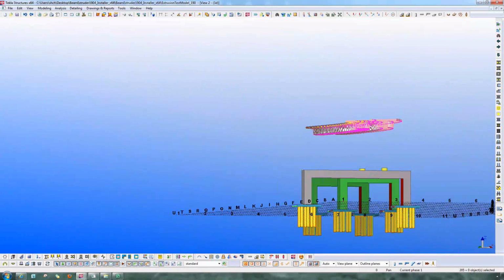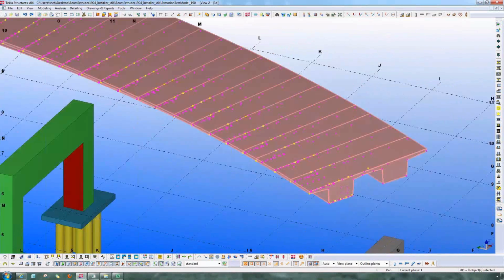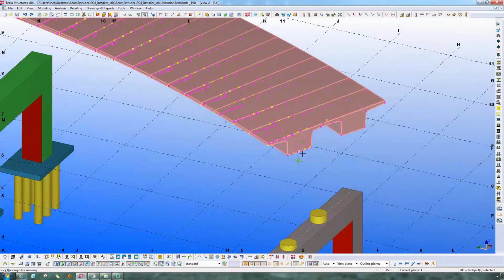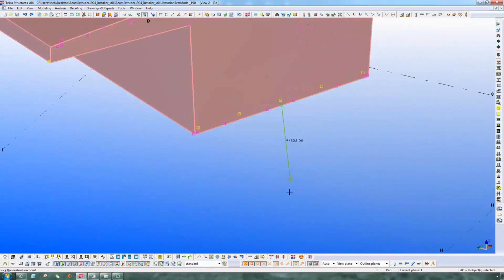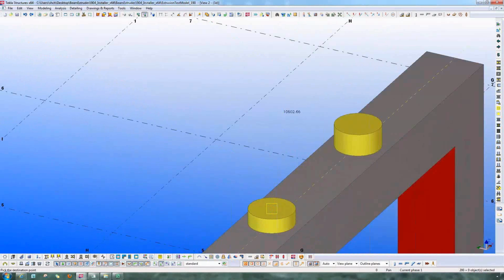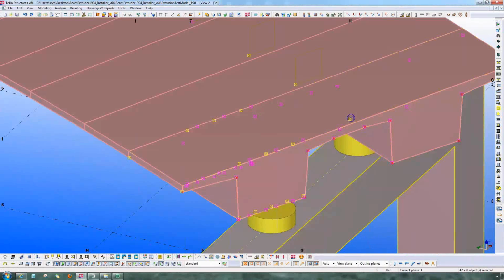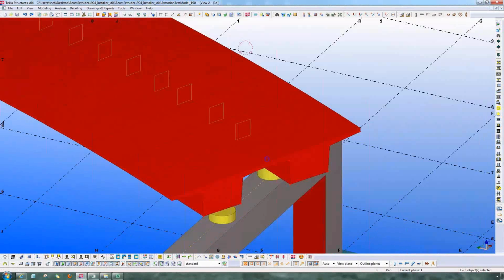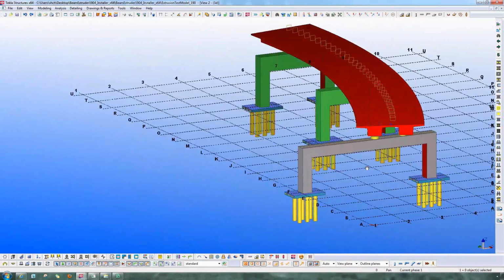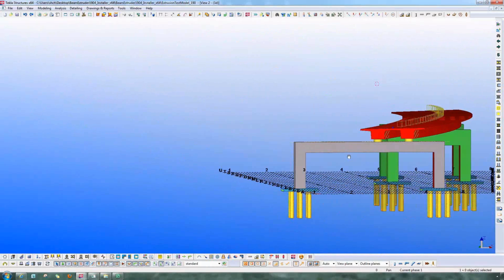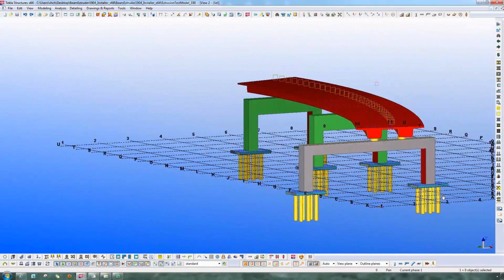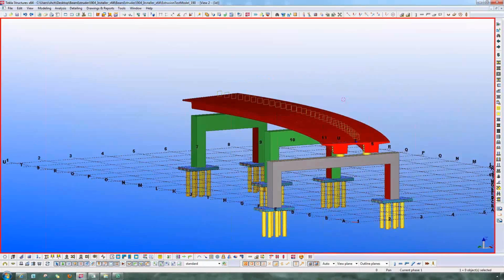So what we can do is very quickly move that part also. I selected the deck portion, and we'll be moving that by selecting the position. Okay, it's selected. We can keep this properly on the bearing pad. Now we can see the reinforcement, the deck portion modeled in the curved part with the proper slopes, and one can adjust by moving the deck. So let me just redraw.